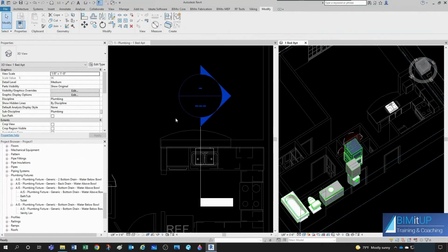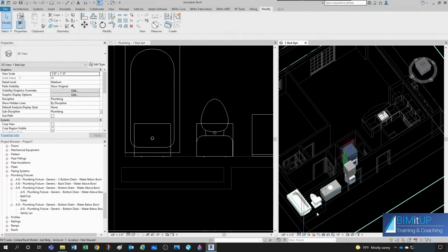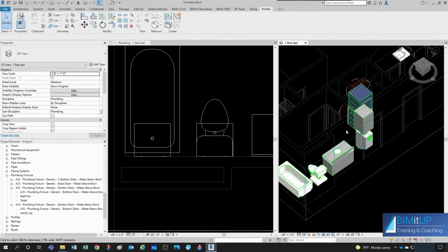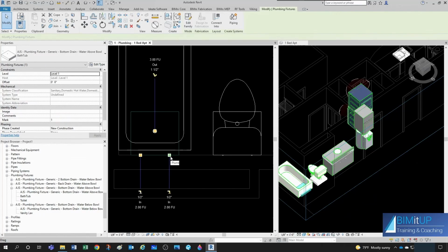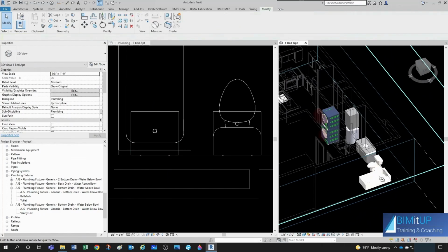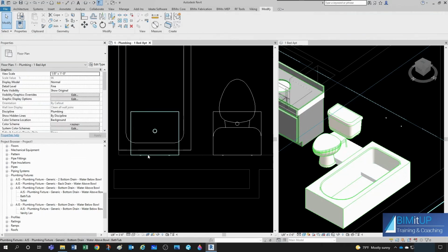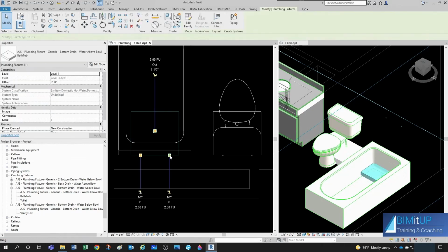We close this section. So let's start with the hot water. I always like to start with the hot water because then I can pipe to the water heater and then I can pipe all the cold water at once. So remember, if you're looking at the faucet or the mixing valve from the interior wall, your left side is always going to be hot water and your right side is going to be cold water. So this guy is going to be cold water and this guy is going to be hot water.